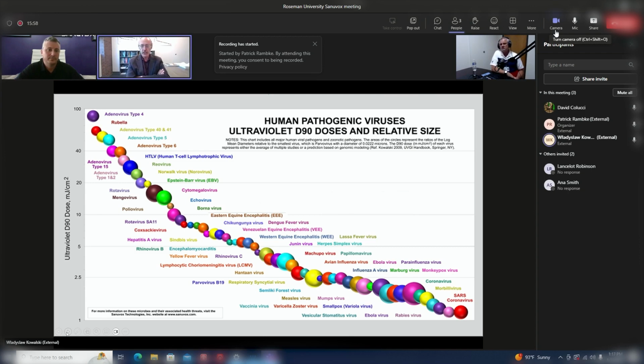Yes. All air disinfection systems placed in ductwork must be sized precisely. They must be engineered for the particular airflow as well as for the duct size. So these factors are a matter of engineering. All the information is available. Systems can be sized to deliver a particular level of performance. And the minimum level of performance is typically 99.9% for air disinfection. Okay, great. And air disinfection systems can take out viruses at high rates.